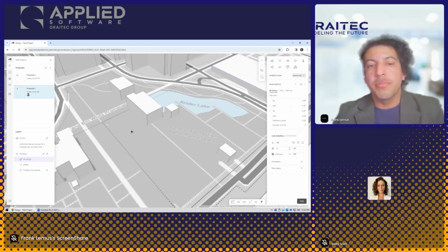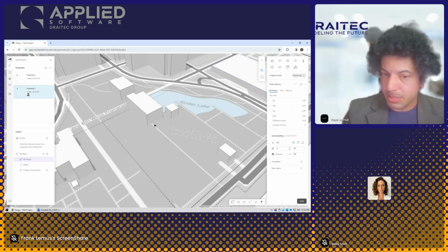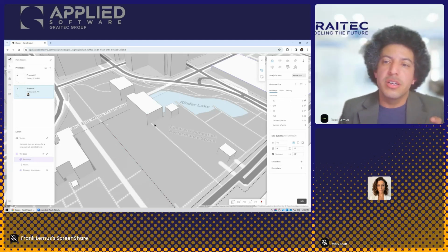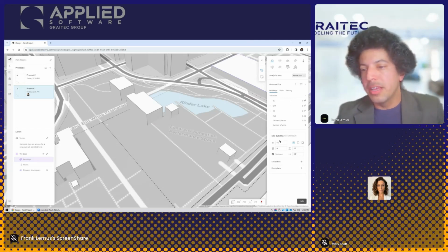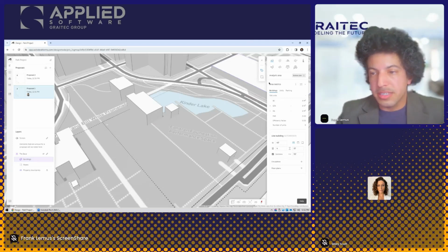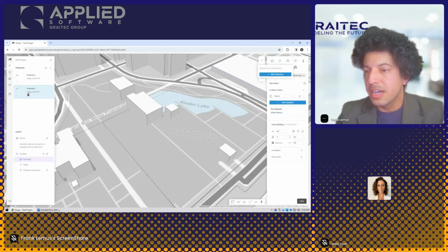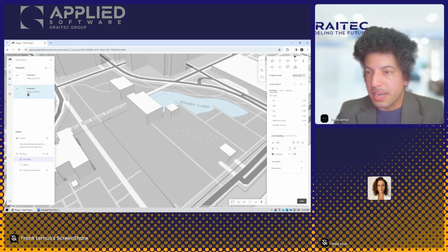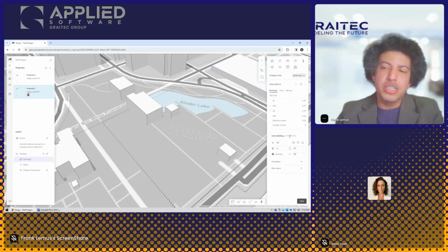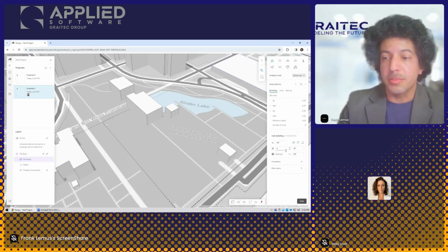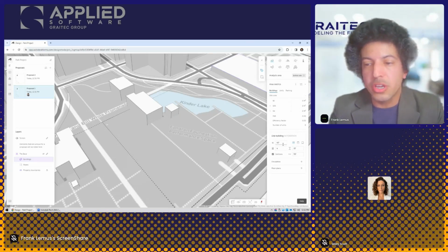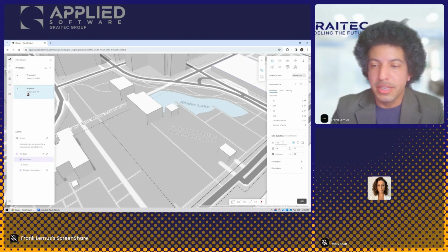Now, anything you do in Forma, when you initiate a command or when you select an object in Forma, your first reaction should always be to look at the right panel and to go to the very bottom. Okay, because things like the area metrics, this portion right here will be adjusted as I select different objects, right? However, because I'm currently in the command, I can see something extra down here. Line building automation. Automation usually gives you the idea that, yes, there's something extra going on here. And this is actually where you're controlling the geometry and the way it's shaped. So let's just take a look.